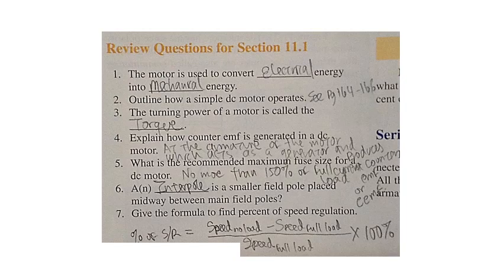Question 5. What is the recommended maximum fuse size for a DC motor? And this is per the NEC, no more than 150% of the full current load.